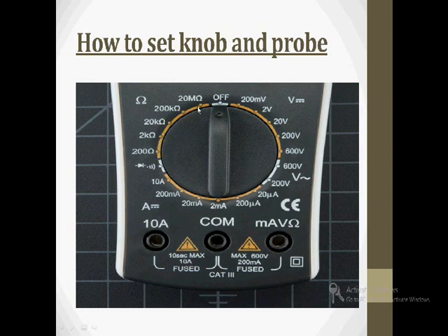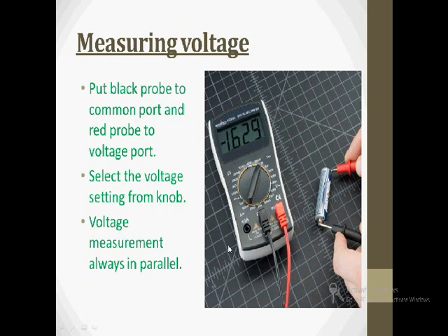It is a good practice to start from the smaller one and keep on increasing. And this applies to DC voltage, AC voltage, and current also. This is all about the selection of knob and the selection of probe. So next is measuring voltage.